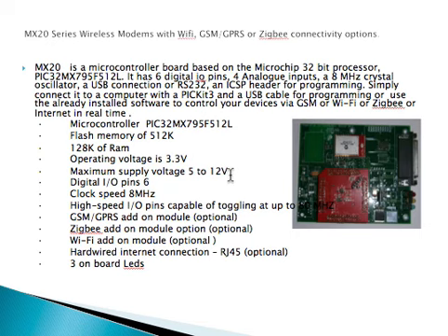Normally I would suggest if you're using the GSM option, use the 12 volt power supply. It's got 6 digital input outputs. Also it's got 2 relays. If you've got devices which need more voltage to control, like a fan or a light, you can use the 2 relays to feed and control these devices.